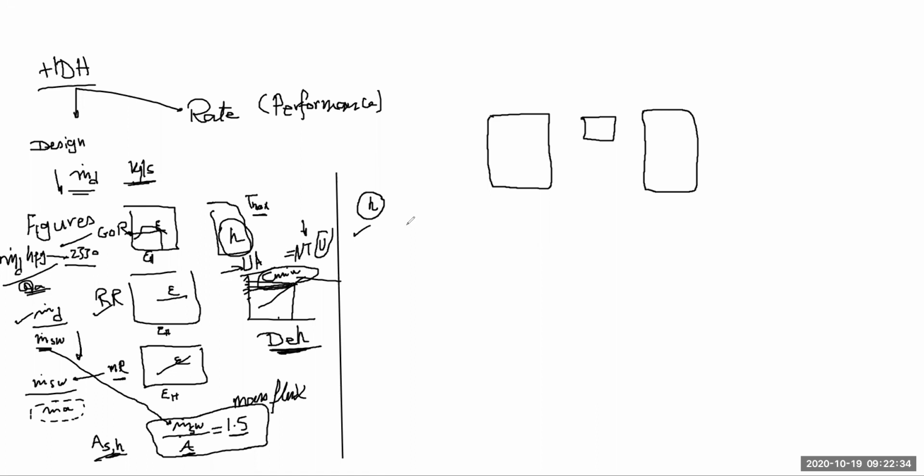What you would be expected to do is to be able to run the energy balance and mass balance, of course, for the system. The only mass balance that we would have, now I'm talking about a water heated system, is that m dot water coming to the humidifier is basically m dot brine plus vapor, which will be carried by the air. So the mass balance here is that m dot water entering will be m dot brine rejected plus m dot evaporated.